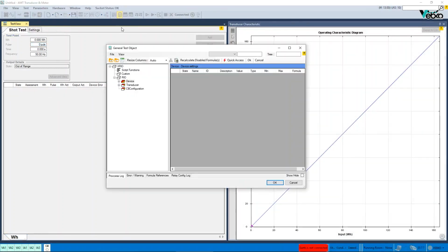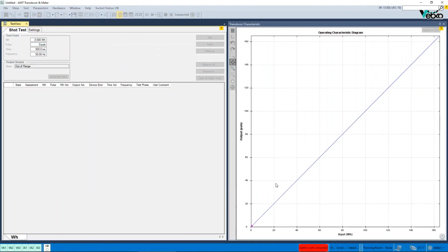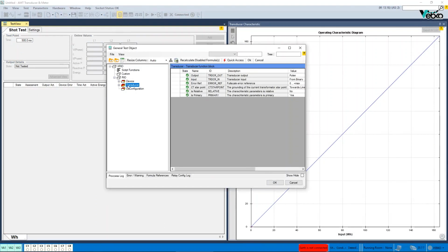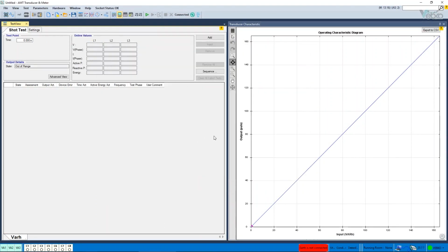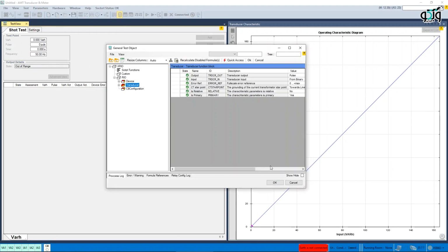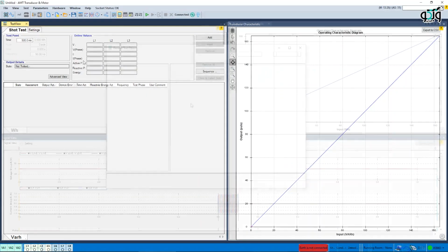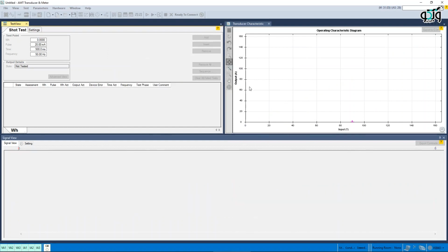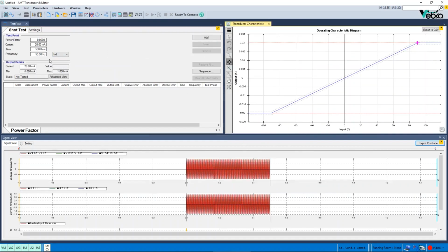If you select one of the functions of Watt-hour or var-hour from the Transducer Properties page and put input on Read from Binary mode, the test points are changed in the Test Point section. In the Power Factor test, Advanced View, Generator Settings, and Power Factor Sign sections are corrected.